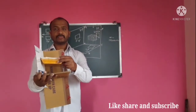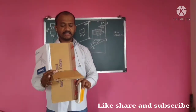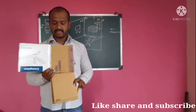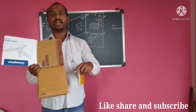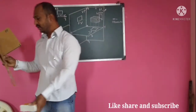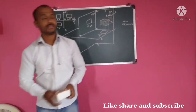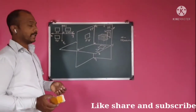So right hand side view on this view, and when I rotate it like this and like this, then here it will be the front view, top view, and on this side there will be the right hand side view. So this is the first angle method, in which we are going to draw the views like this.